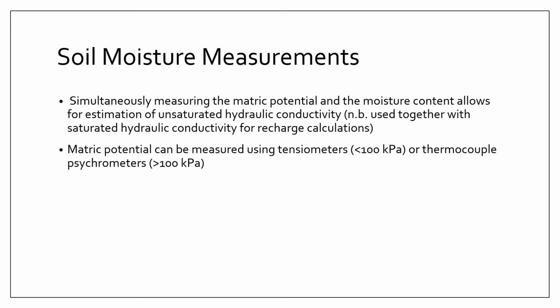Another method is soil moisture measurements. What you do is you measure your matric potential and then you measure your soil moisture. And from there, you can eventually derive the unsaturated hydraulic conductivity, which can then be used to model your recharge.